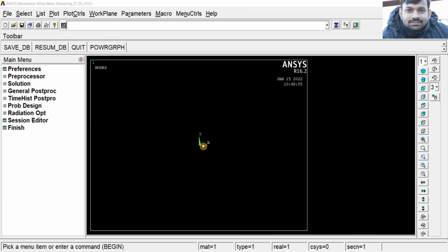If you want to move or pan the object, we can directly use these buttons: pan left or right, up or down, and so on. Then we can rotate about 3 axes, about x, y, z, in positive x or negative x, and similar directions. Okay, then we have the dynamic model mode for switching the mouse button selection.